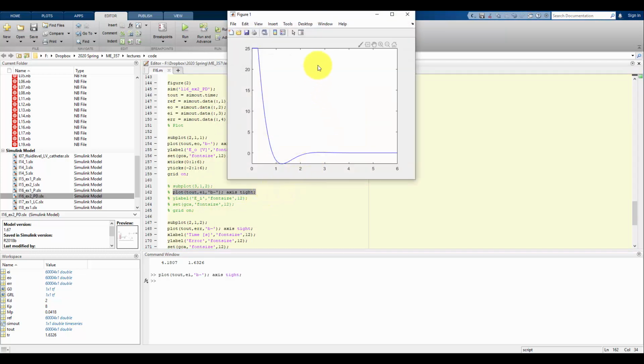All right, so we see here with the limiter on, the most the input can be is set to 25. Again, I just picked that arbitrarily, but the controller is demanding more, but the system is only supplying 25. And then the input goes down, and then the input eventually goes to 0 into the system as it levels off. Right? But that limiter is why we have that hard cap there of 25.